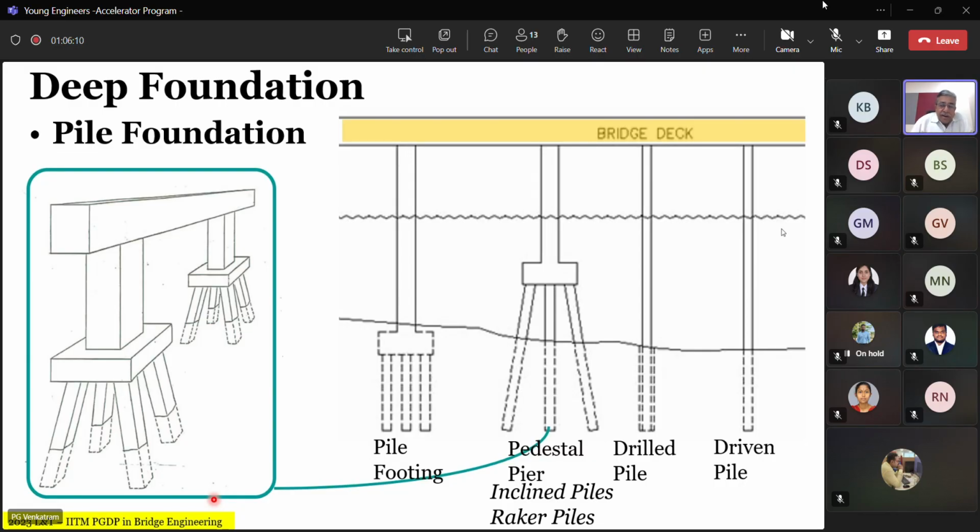Obviously, friction is there. Okay, but I said there's a mechanism by which you can estimate the pile capacity of a driven pile. Do you recall how it is done? You've heard of the Hiley method? Energy transfer, number of blows, penetration rate. I want you to do a little bit of reading on that part of the pile foundation to refresh what you may have missed. Okay, so that's a mechanism to do it for driven piles.